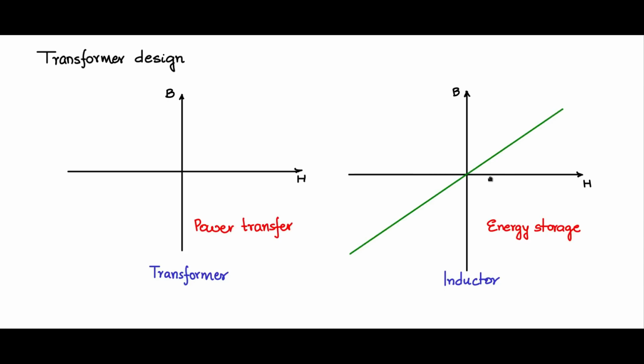In the case of the inductor, in order to have as high energy storage as possible, we discussed that we would like to have the mu, the permeability, as low as possible. So the core is designed to have as low mu as possible so that you have very high magnetization current. The magnetization current, Ni by Lm, should be very high so that the maximum energy that is stored in the core is half L i square. So more energy gets stored because the energy is proportional to the magnetization current.